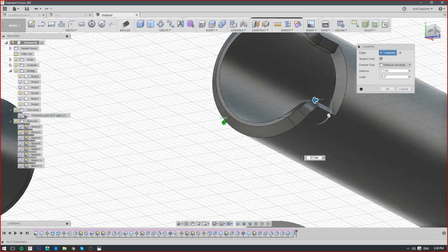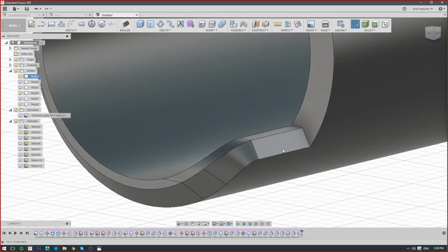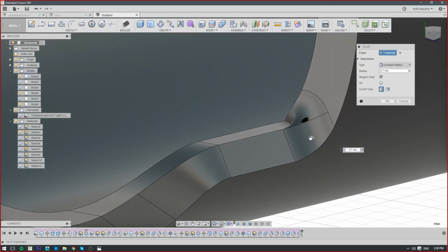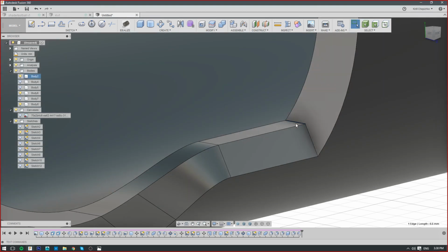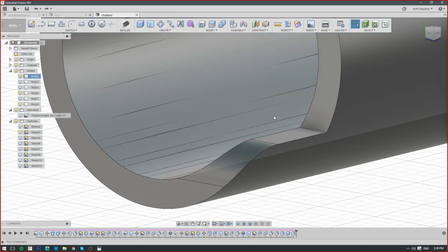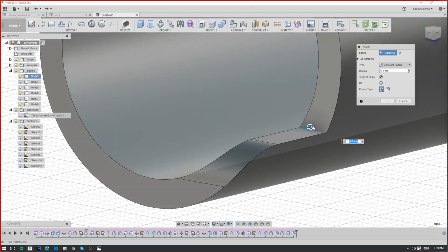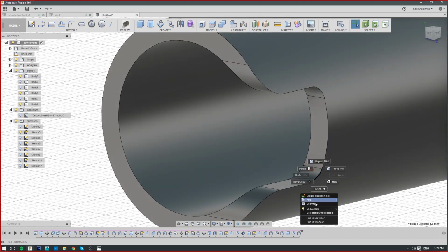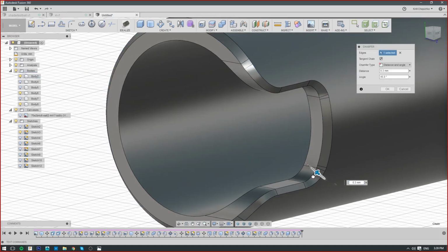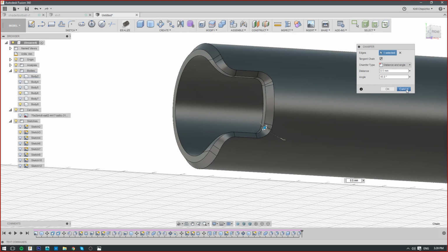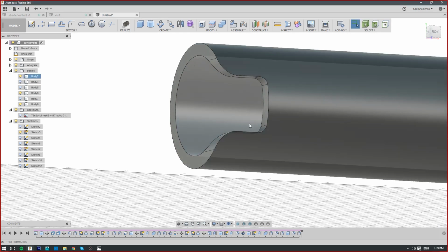Yeah, exactly. So clearly it matters, but then I have a problem here: how do I go about this? This looks broken. If I fillet this, it will also look broken. So you have to think about it. Maybe you should also fillet this before you do that chamfer, like that. Now you create that lip, and it goes nicely through the whole thing, and it just looks better. So the order of things matters, not only for the look, but they also